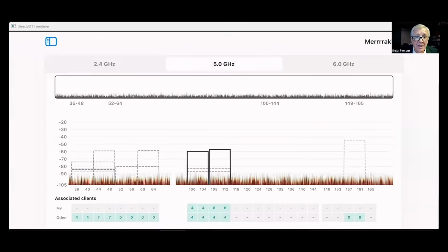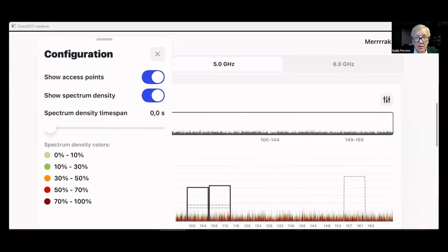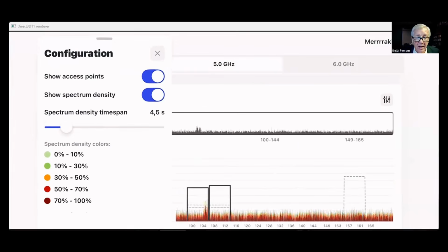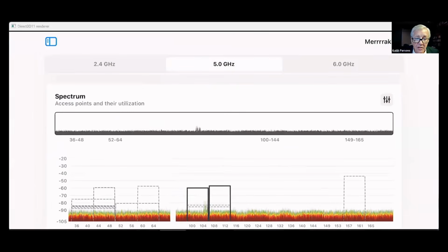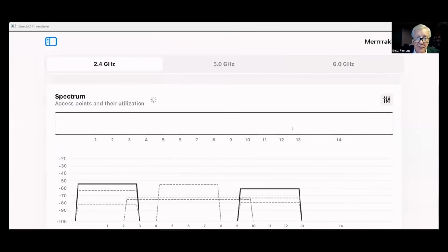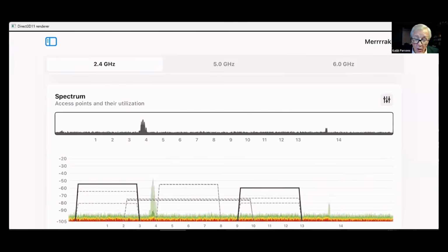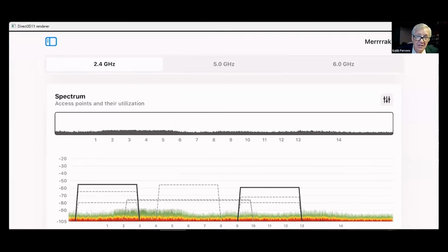When they go away, that means we don't see a beacon, which means you trip that threshold in the Wi-Fi algorithm. So getting used to that is a very useful way, when you don't have a spectrum analyzer, to see how bad something's getting. Or the flip side is the beacons are still transmitting on top of stuff, and your Wi-Fi is still playing nice.